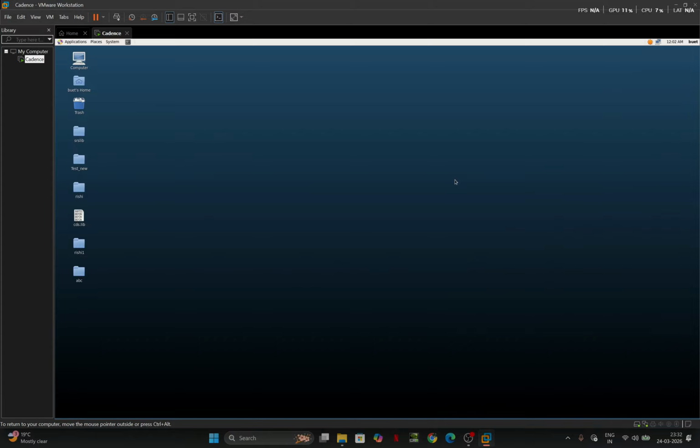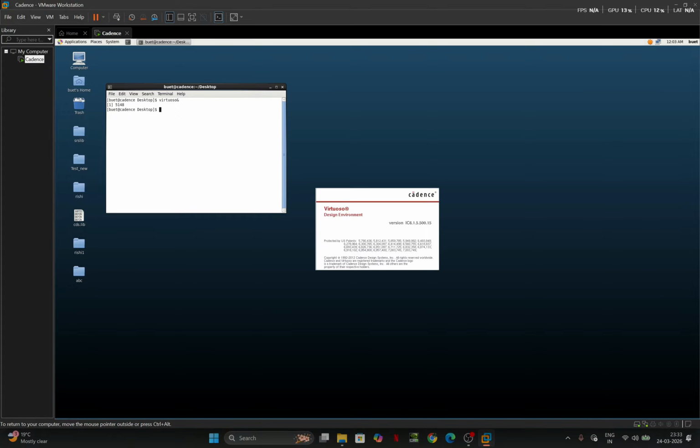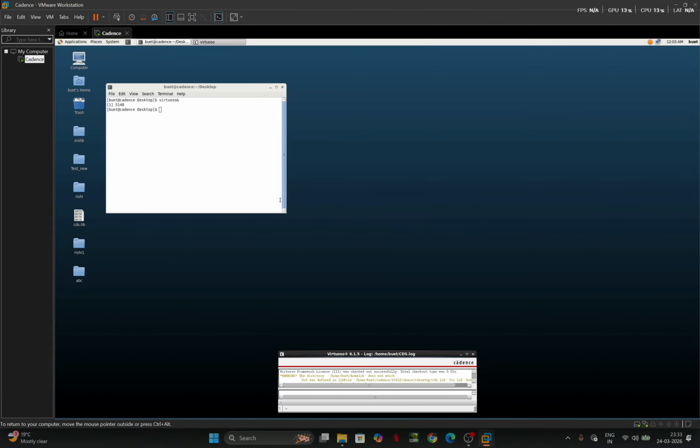Hello everyone, myself Rishi, and today we are going to learn about a new software named Cadence. Firstly, for opening Cadence, we go to the terminal and run the command virtuoso, and this will open our workspace where we are going to create libraries and cell views.